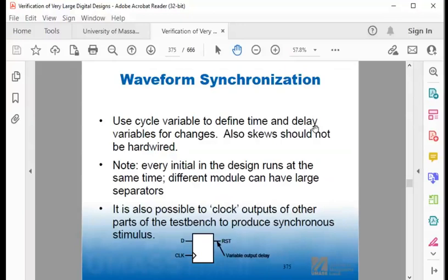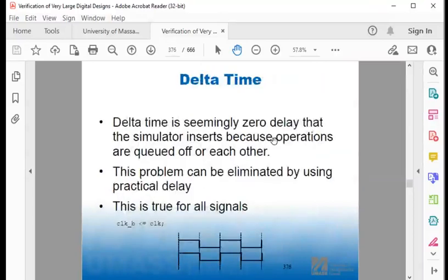So test, and this is something you do at gate level too, make sure without looking at it that the designers have synchronized reset properly. You need that as a verification engineer, right? It's important in system design, but it's also very important in verification that the system is in a known state before you start testing. And that's what reset does.